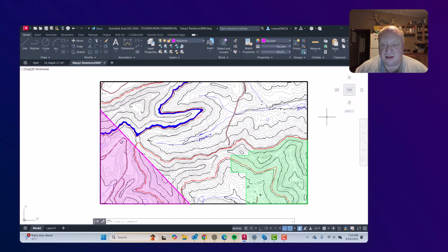So with that, let me make this one last correction, and I'll get this published on the website as well in PDF format. And I'm going to print these actually both in 200 scale and 500 scale maps, meaning that if you were to print these on paper or look at them at 100% scale on a PDF reader, your more detailed map will have 1 inch equaling 200 feet as the scale, and the other map will have 1 to 500, so 1 inch would equal 500 feet. So you can print those off.